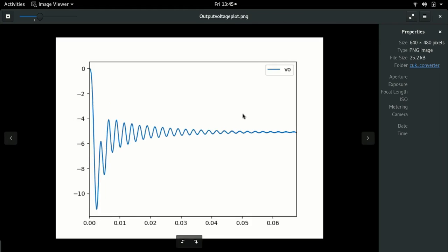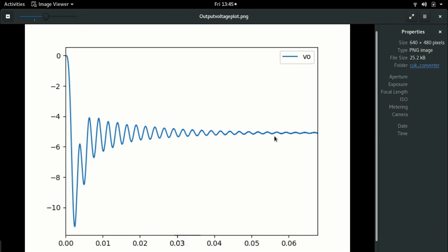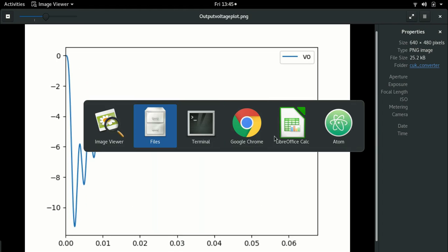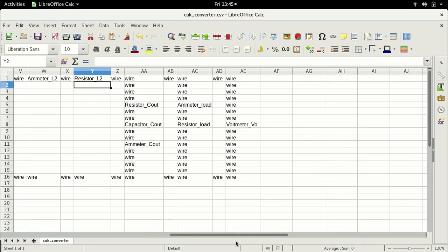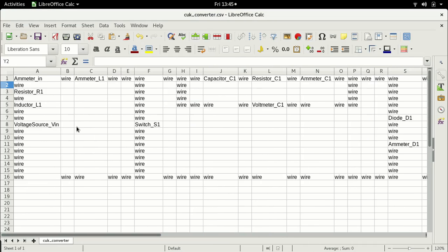So first things first, you see a negative voltage, and as I said, this is expected. The reason, because that's how the Cuk converter is. Okay, remember, how does it work? Switch is turned on, current flows in the clockwise direction. The capacitor will also discharge in the anti-clockwise direction. Both of them are feeding current into the switch. When the switch is off, the capacitor charges, right?